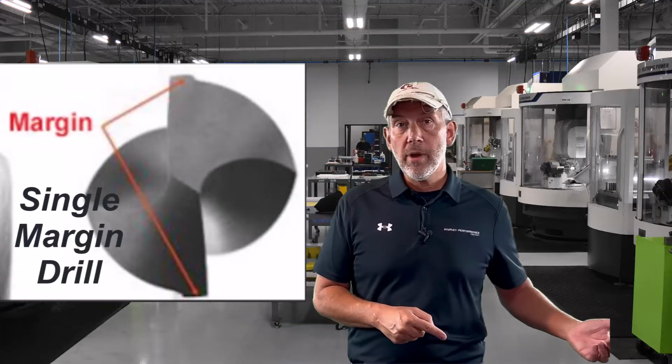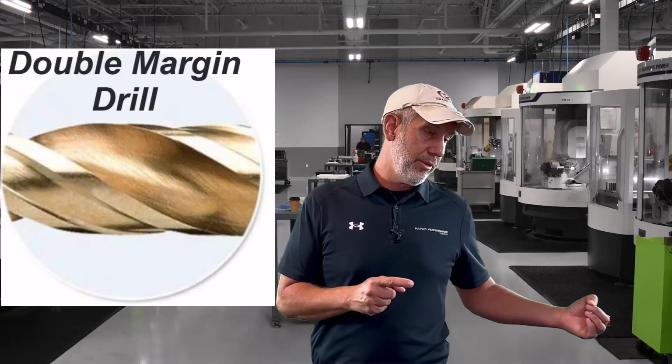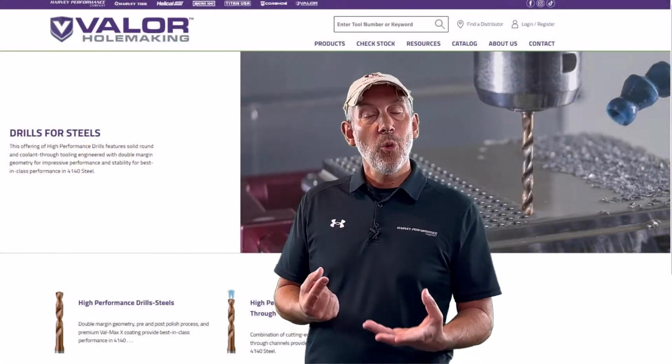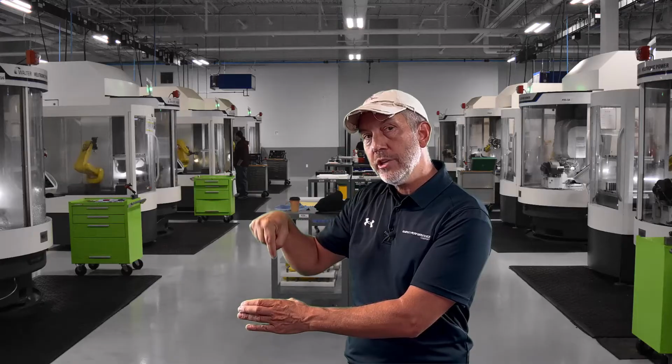Now, some people put 1 margin, some people put 2, some people put 3. Our drills for steels have 2 margins. Why is this beneficial? Why does this make a great hole quality? Because if you put a pilot a little bit larger and you drop a double margin drill down into that pilot, guess what? It acts like a bushing. It really starts your hole off nice and straight, and that pilot will act like a bushing and guide that thing all the way through. So look at double margin drills sometimes. And if you have a double margin drill, you might want to hit a pilot. So again, a way to make a good straight hole 2 ways.